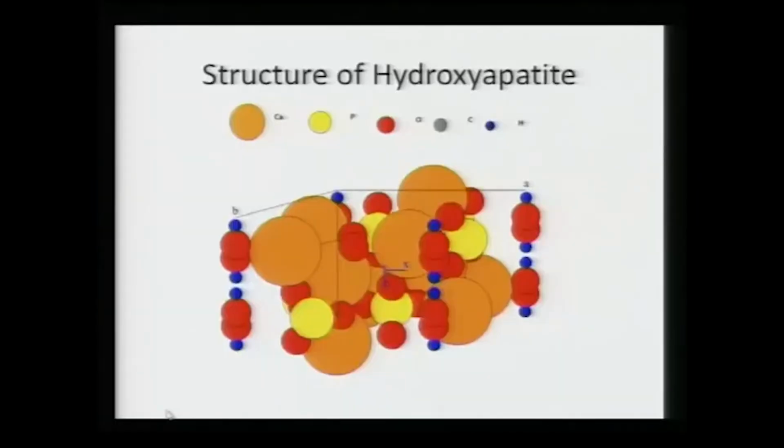So we can see the structure of hydroxyapatite. It is again P63/m. We can see all the calcium atoms just sitting as such. We have Ca10, so we have 10 atoms of calcium, and Ca10(PO4)6. So we have 6 atoms of P which are sitting as yellow atoms. Then we have oxygen which is again sitting at certain locations, and H. So H is basically present as OH twice.